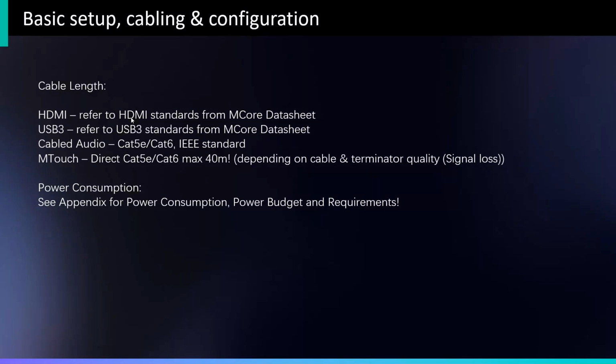You saw before, for example, for screen sharing via the M-Touch, we require USB 3.1 with DP possibility. DP is DisplayPort, and of course, when you want to do, for example, also BYOD using USB-C on an A40 or whatever, the notebook has to support it. It doesn't make any sense if the notebook, for example, doesn't support DP and you want to achieve something.